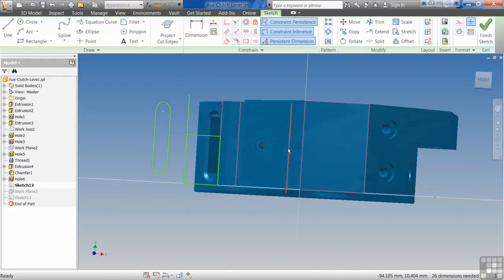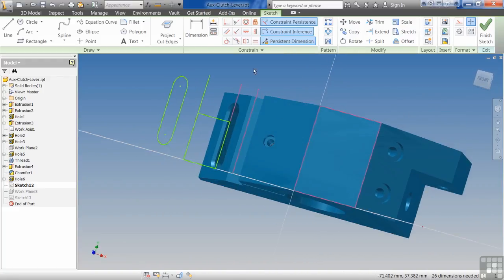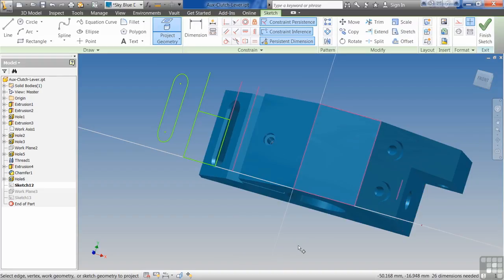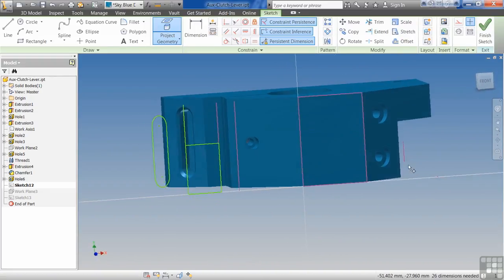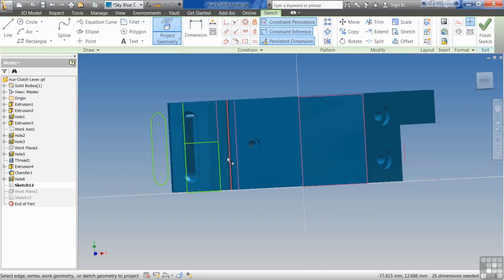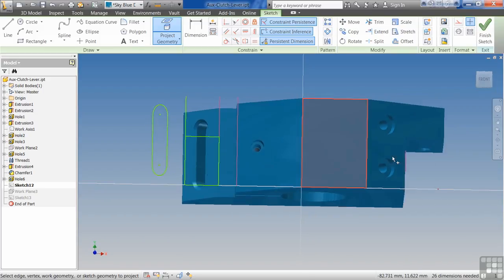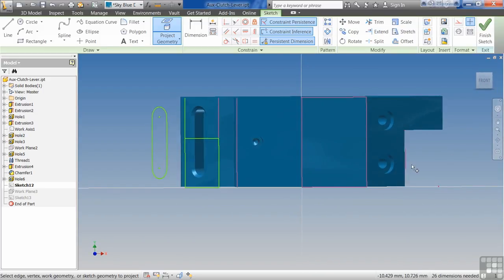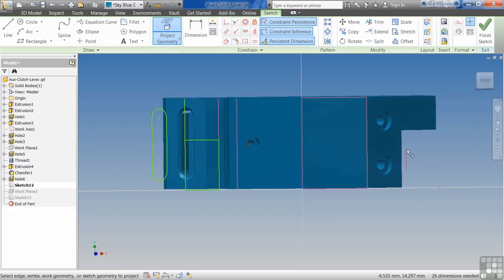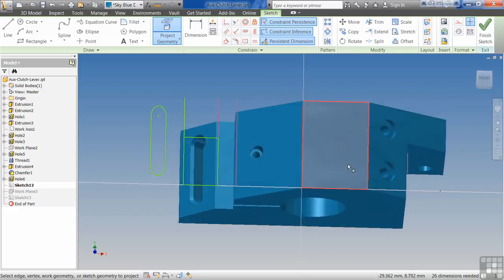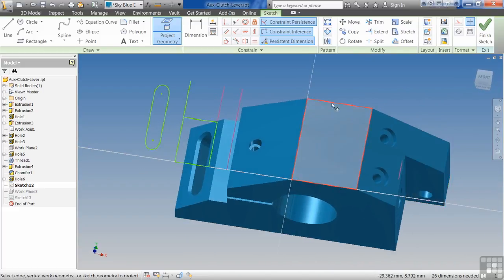If you are projecting a plane like this, we could do things like project this hole right here. So for instance, if you wanted something that would be aligned with the center of that hole that was going through that part, we could just project that hole. You can see just that one line shows up, and so we can use that. And the same over here. Say project, and I could project this hole, or I could even project the whole thing, or it'll give me both ends. Same with this large one.